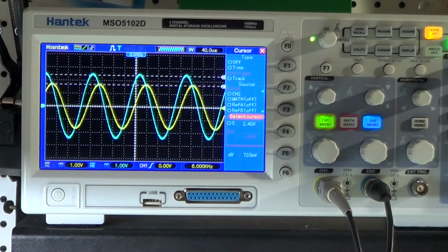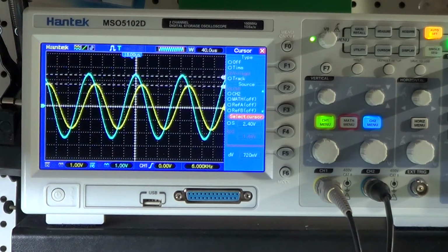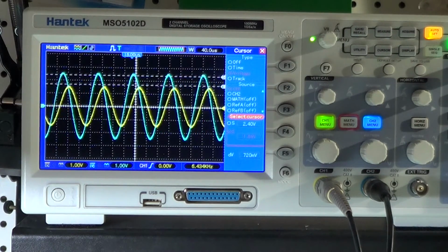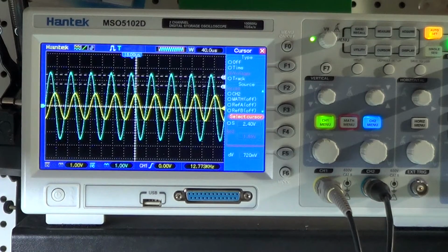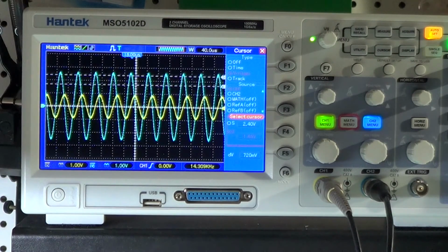And this is because we put in series two identical first order low pass filters, whose original cutoff frequency was 16 kHz. So you can see now how things change from the perspective of second order filters. So let's now keep increasing the frequency and let's see what happens. As you can see, things keep changing very fast.